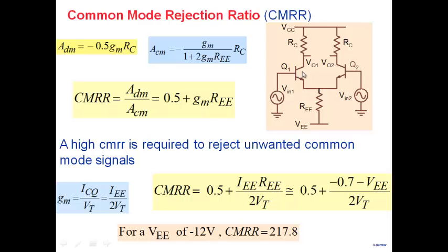So if I want 1 milliampere here, all I want is 2 milliamperes to flow here. And if you want 2 milliamperes to flow here, then you appropriately choose RE. So another way of biasing that I can think of is, suppose I take RE out. And instead, suppose you want to bias it at 1 milliampere here, I put a 2 milliampere current source. If I put a 2 milliampere current source, what would happen? If it's a very good current source, fine, biasing is okay, no problem.